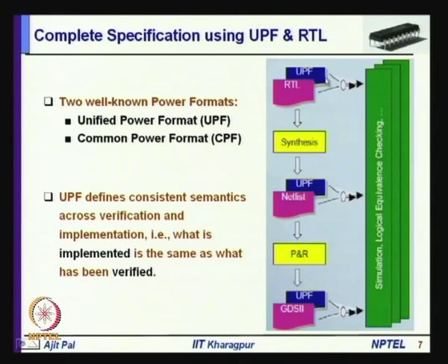So, you can see it can be used throughout all the design steps like synthesis, placement and routing, and you will be doing simulation, you will be doing verification, and also you will be performing sign off, as we shall see. So, UPF along with your VHDL coding or RTL coding can be used throughout the synthesis cycle, starting from system level to the layout level.